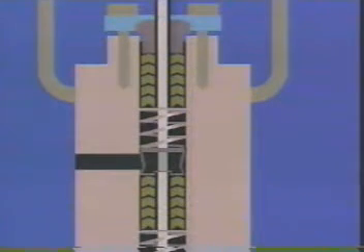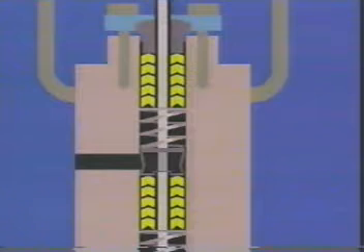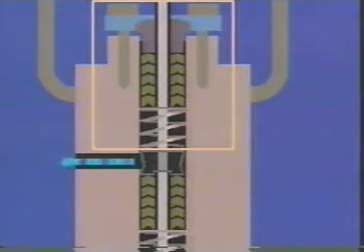Note that this design has two completely separate, independently compressed packing sets sealing the valve stem. This particular design uses spring-loaded chevron-type packing. In many applications, the space between the sets of packing is vented to a safe disposal point, such as a special waste tank. While leakage may exist, the leakage is not past the valve stem and into the environment. Another approach that can be used to seal this type of valve is to pressurize this space with an inert fluid.